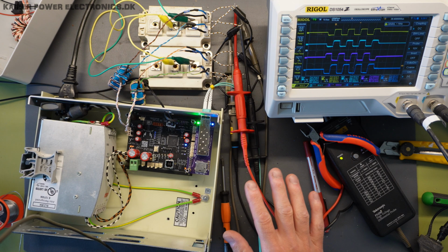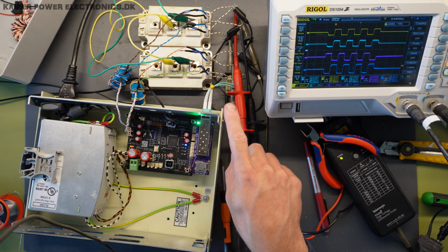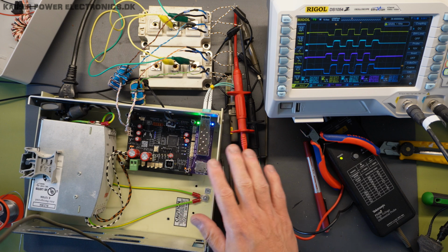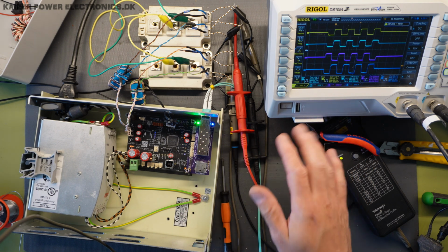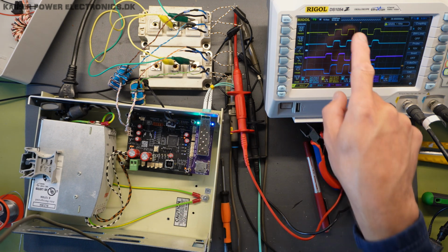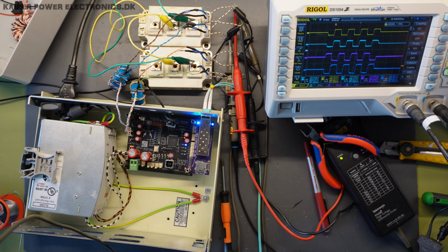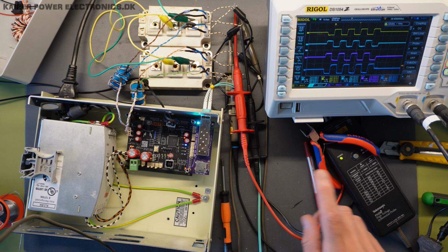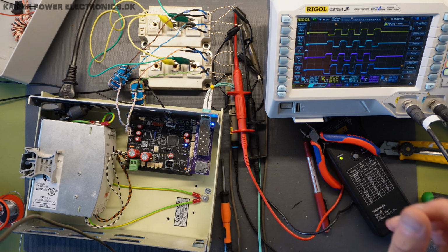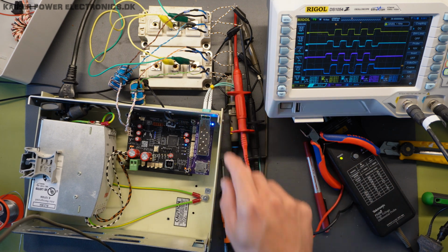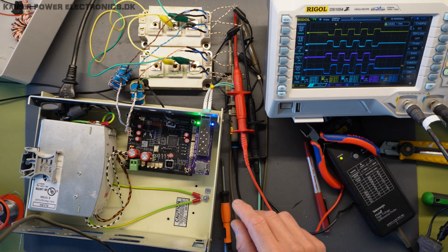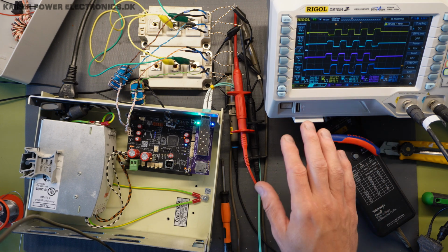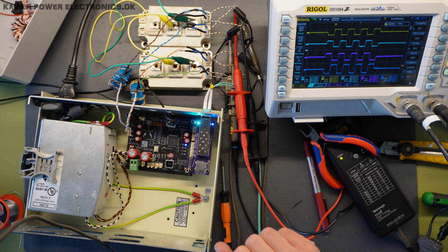A good sanity check to do when changing the phasing does not work well tells us it's something with our measurement. And quite right. If I look through my settings here, then channel 2 has invert on. I discovered this by taking my differential probe here, and the other one is a 2-channel isolator sitting up here on the bench, and just connecting that up to channel 2 and got the correct signal. So that was just a setting on the oscilloscope.